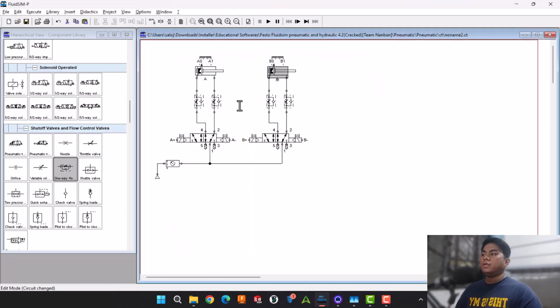So this is called the distance ruler. The distance ruler is like a guide for the positioning of our sensors. Sometimes it's a reed switch, sometimes it's a limit switch. So it's a hint: if it's in the middle, maybe the component used in the pneumatic diagram is a reed switch.